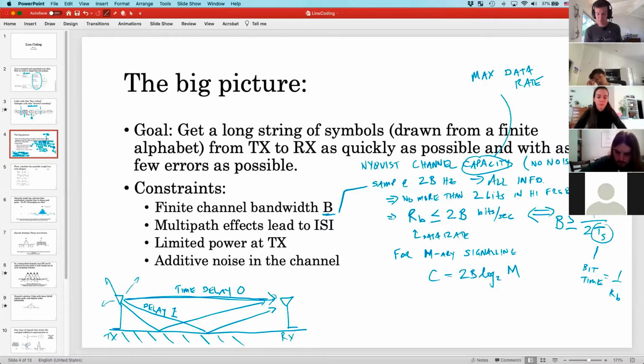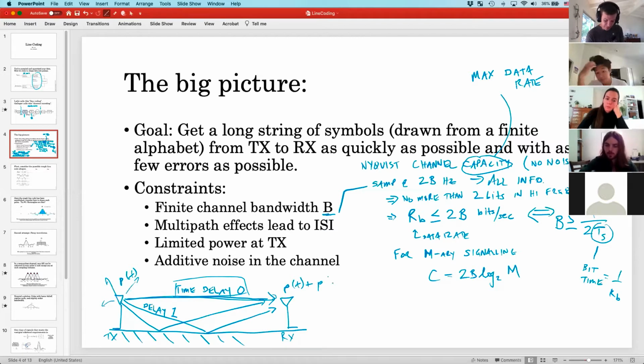Does that make sense? So what you're going to get is kind of the baseline delay. And in fact, so far in this course, I've been just assuming the only time we actually considered this was in the radar ranging problem. But in truth, there's going to be delay introduced all over the place. If you have a dominant line of sight, then it's usually good to model this pulse as just happening at time equals 0, the same time that this pulse happened. But what we're going to do is add to that a pulse of t minus t delay 1, and then a pulse of t minus t delay 2.